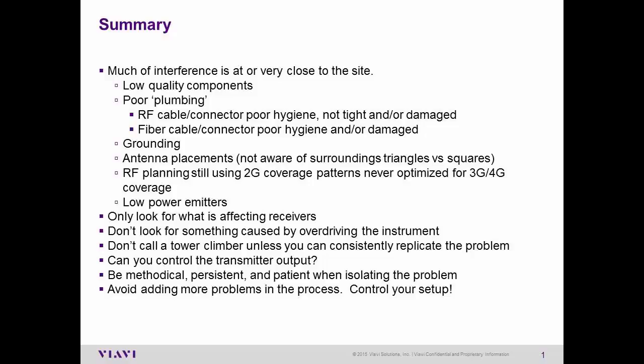Be methodical, persistent, and patient when isolating the problem, and bottom line, avoid more problems in the process. Control your setup, meaning don't think that you've found a problem when in fact the problem is your setup. So be very confident and also be very careful. Don't be too quick to start disconnecting RF connectors, because you could be adding more problems instead of actually isolating where the real problem is.